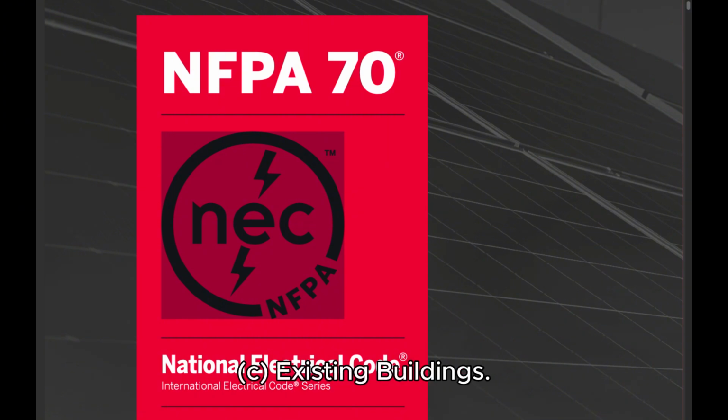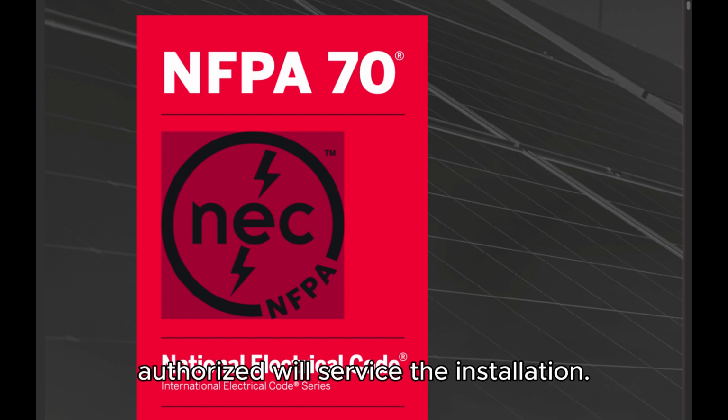(c) Existing buildings. In existing buildings where electrical equipment is being replaced, Condition 2 working clearance shall be permitted between dead-front switchboards, switchgear, panelboards, or motor control centers located across the aisle from each other where conditions of maintenance and supervision ensure that written procedures have been adopted to prohibit equipment on both sides of the aisle from being open at the same time and qualified persons who are authorized will service the installation.